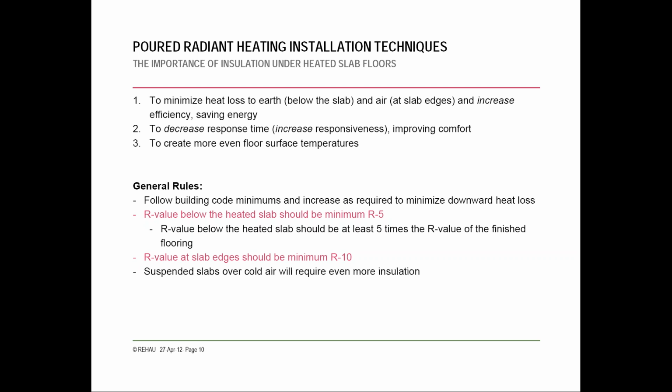I do not believe there is a requirement for insulation throughout the whole slab, but depending on what code you're conforming to, that may be something you need to consider. These are general rules. As you can see here, R15, R10. Obviously it depends on how much money you're willing to spend as well, and what type of insulation you're using.